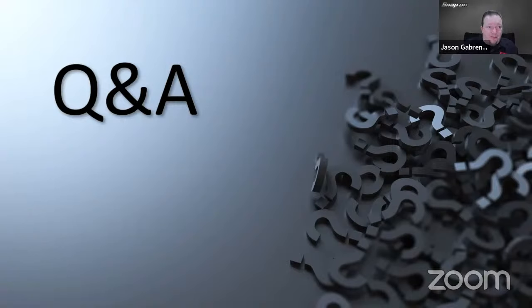Joe asks, aftermarket parts like headlamps, would they need coding as well? Yes. Anytime I would normally need coding, like for a brand new part, even a salvage part like a headlamp, it would need to be coded to the vehicle unless the control module is replaced at the same time. Basically, what you're doing with the coding is you're telling the control module how this particular piece works. Every piece is going to be a little bit different, so you've got to tell it to go in there and actually do that. It's kind of like the pairing, the mating of the two pieces. So yeah, definitely if it was an aftermarket headlamp.